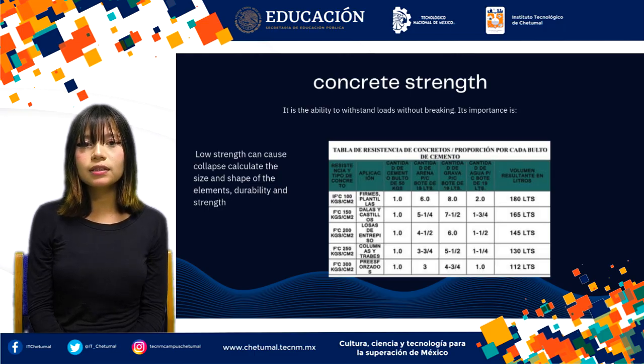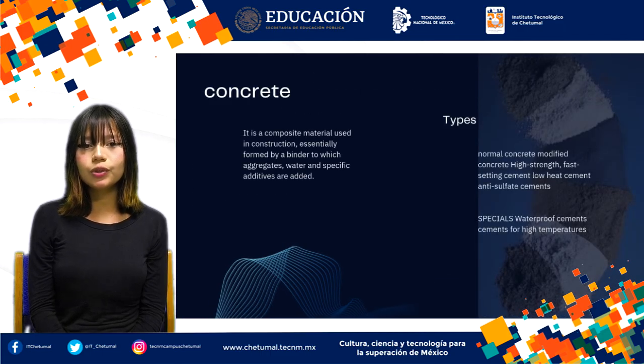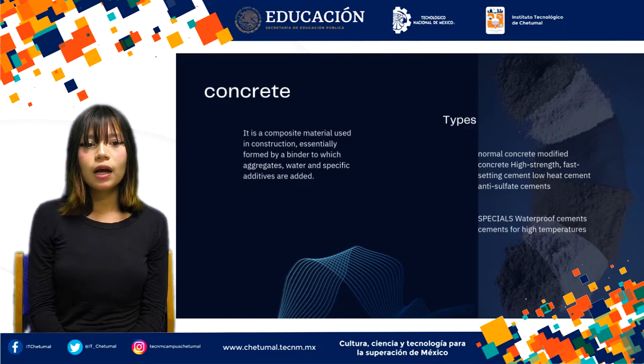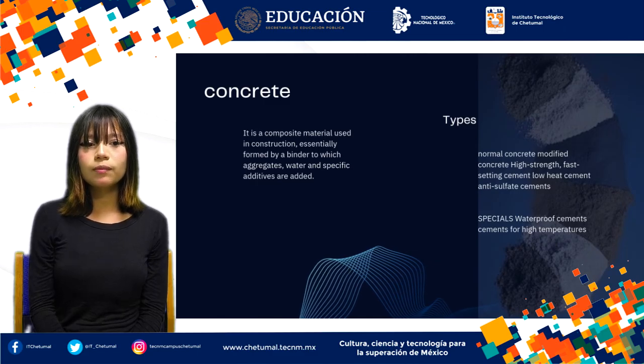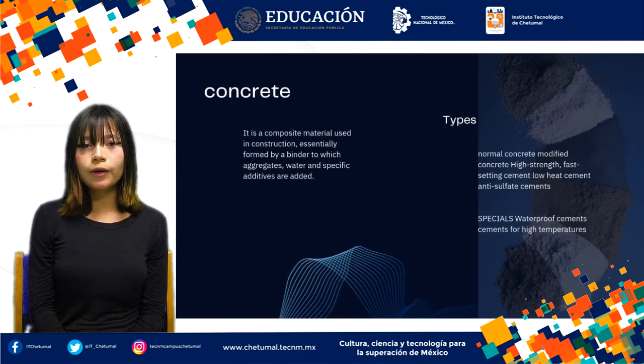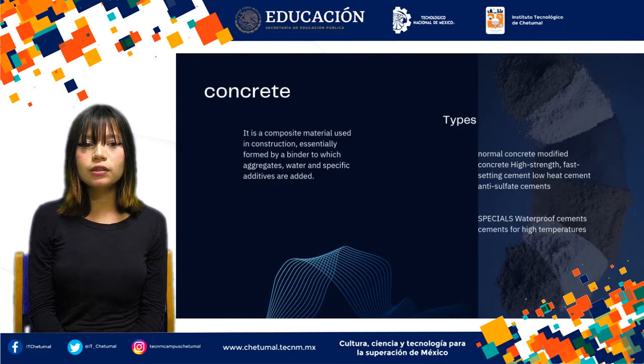The foundation base is a thin layer of concrete placed at the bottom of the excavated trenches before starting the foundation construction. Its purpose is to provide a uniform and clean base on which the foundation will be built. Materials used. The base is made of a simple concrete mix without reinforcement, with a suitable water cement ratio to ensure its strength and fluidity.